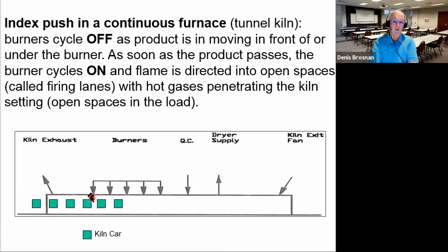Now, flame impingement not only can thermal shock the product through hot spots, it can cause reduction effects on the product. In the case of clay products, it can change their color. So nevertheless, index push is very common.